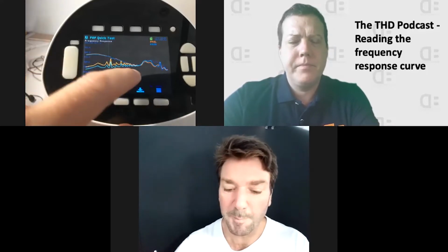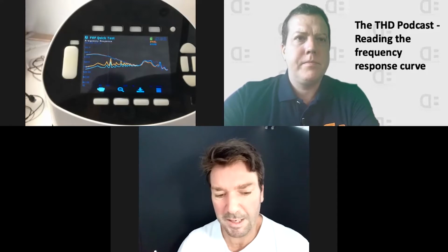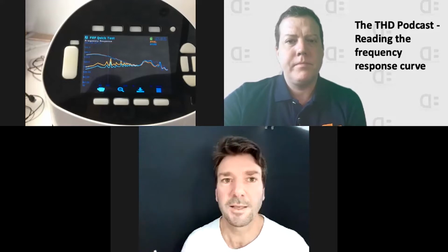So that's enough on low frequency. You can just lift this thing up and down depending on how you adjust that leakage and that tuning. And it doesn't matter too much about the driver size. Of course, big is better always. You just have more power at your disposal, but it can be done with a small driver. The one thing to point out, though, is if it's a small driver, you'd need a lot less leakage to get the same level of bass. So with a large diaphragm, you could have more leakage. In principle, a large diaphragm would be more comfortable. You could have a larger leakage, less pressure seal, but still get the same amount of bass loudness out of it.